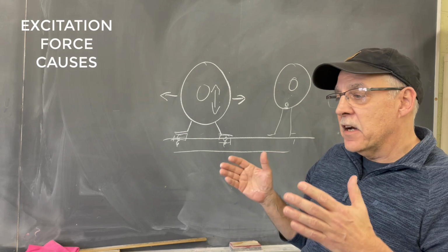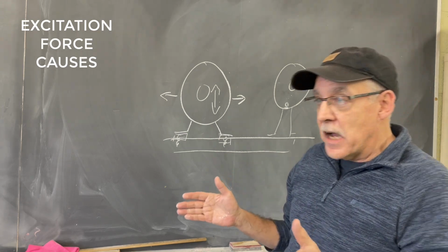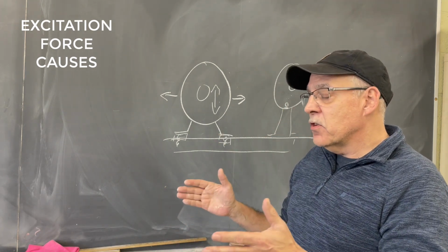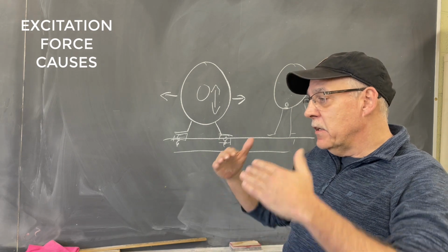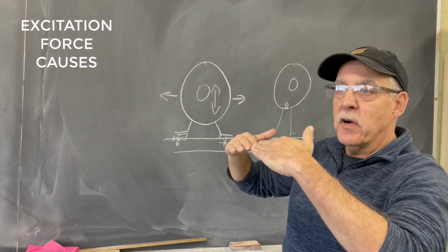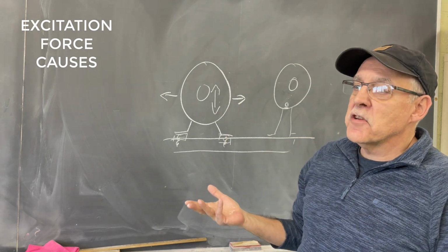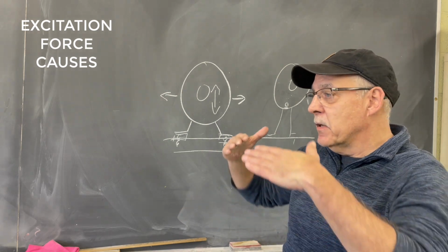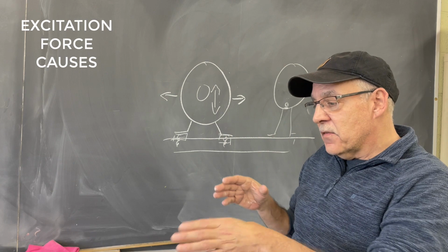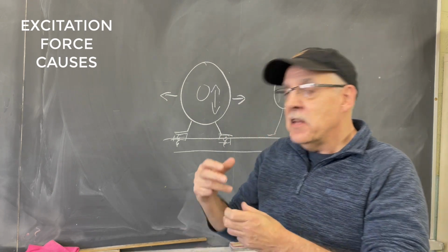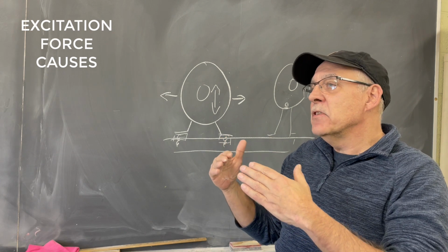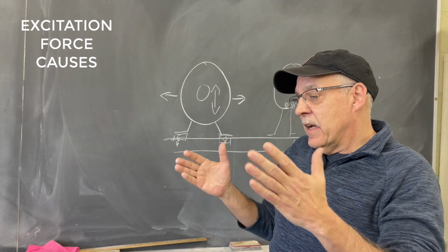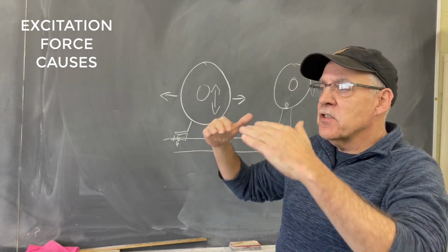Everything has many, many natural frequencies. If you vibrate something, or turn something, at its natural frequency, its ability to stay stiff, to stay together, or not vibrate goes away. If we had something with a natural frequency of 1,000 cycles per minute, and we turn it at 1,000 cycles per minute, all these forces, the stiffness, the mass, the damping, work together. Your stiffness force is at the same kind of speed, and so that stiffness goes away.